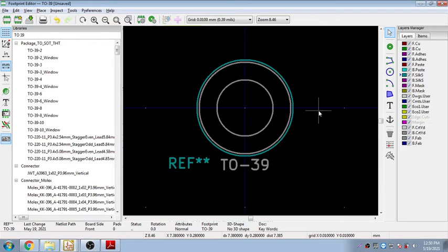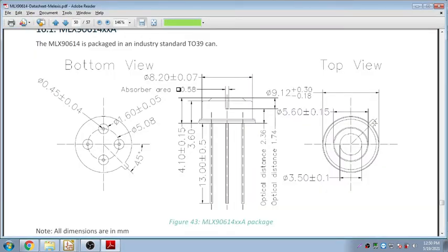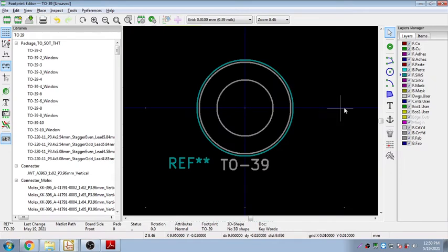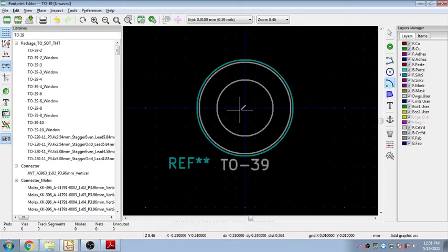That marking, you see the marking is exactly at 45 degrees. From the top view, if I'm going to place this, the marking is exactly at a 45 degree angle. The angle is given over here in this bottom view, they have mentioned it is 45 degrees. So we need to create a marking of 45 degrees. This is the indication of a notch, so we can assume some dimension for that notch. So what we can do is take this arc here, roughly you can take an arc and simply point it towards the center.